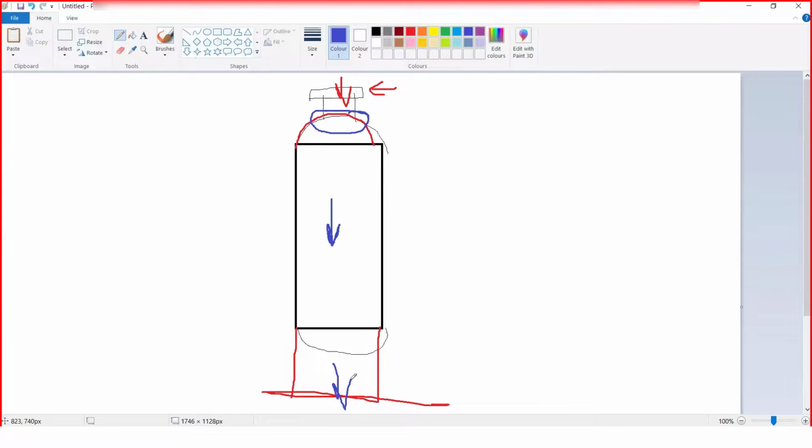It will also push the foundation down. So if you want the nozzle loads to be considered in the foundation calculations, then you have to click that checkbox. Many times in Gulf countries, the soil is very soft at the bottom, and because of these nozzles, if any additional forces are coming, in Indian conditions this will be very easily absorbed by the foundation, there won't be any problem.